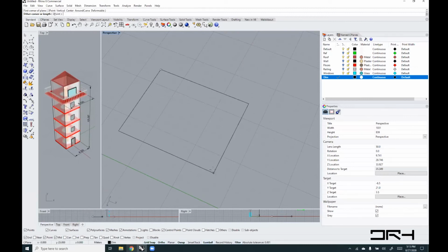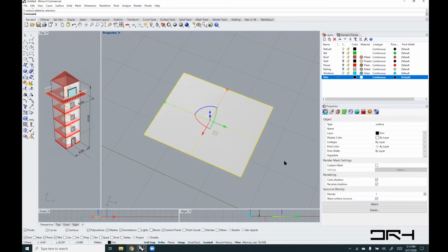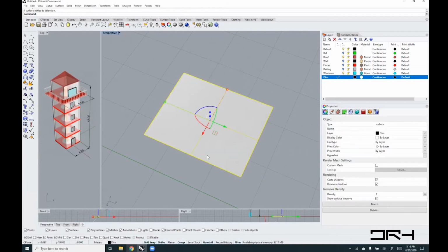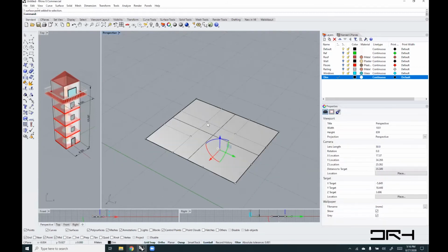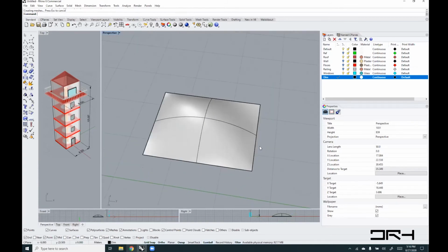So let me just create a plane here. Let me make it more interesting. This is a NURBS curve, so you can rebuild it into multiple points, for more complexity. So there is the rebuild command. I'll show you something along the way. So this is 4x4 and degree 3. Okay. So if you turn on the control points of the surface, you can start moving them and be able to kind of sculpt your surface. I'm just trying to make it interesting when you extract the ISO curves here.